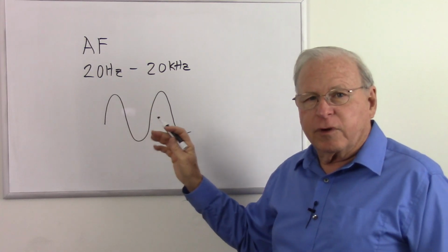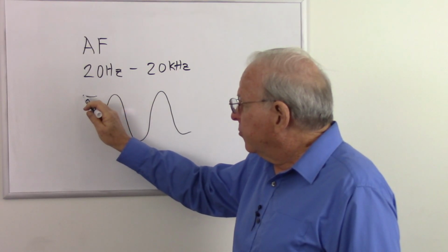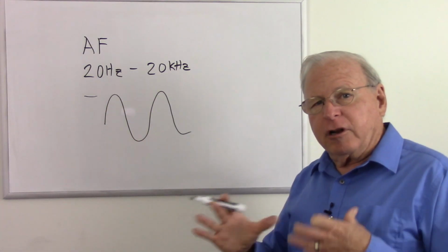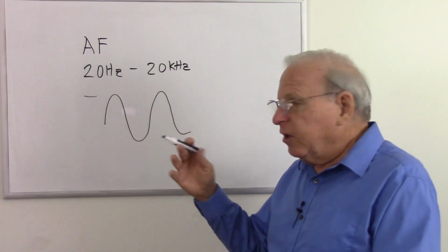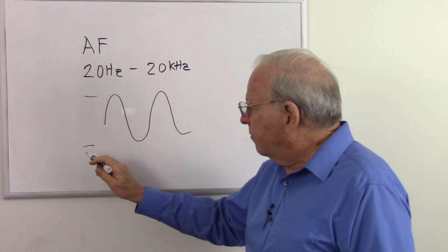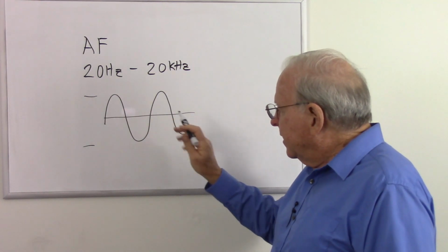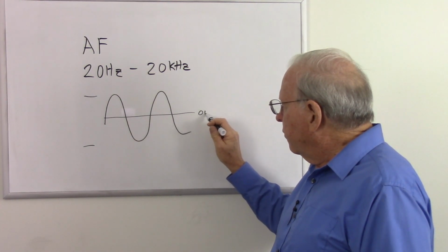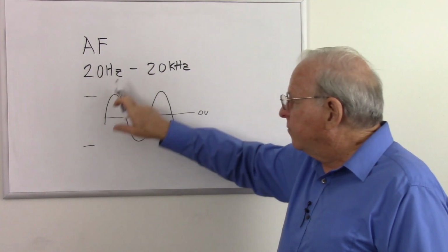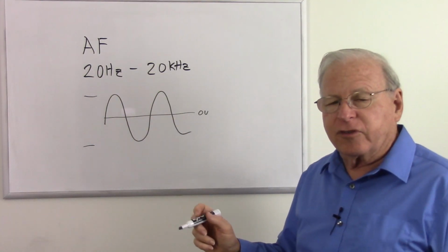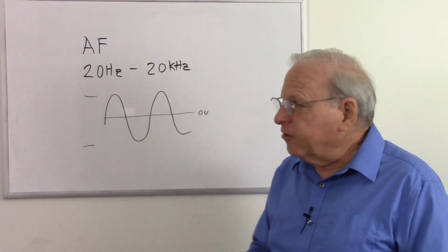What's the range of this voltage? Well, from a microphone, it's going to be pretty dang small, just a few millivolts, but it's going to go up to some peak voltage, and that's going to be determined by how much current is coming out from the microphone and what load is on it. And it's going to go down to some other voltage. In the case of the microphone, in the middle, it's going to be basically 0 volts. So it's going to go up to a positive voltage, and then down to a negative voltage over and over again. That's a single frequency. But what's coming out of my mouth is a very complex range of frequencies.